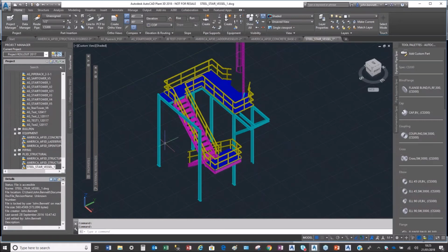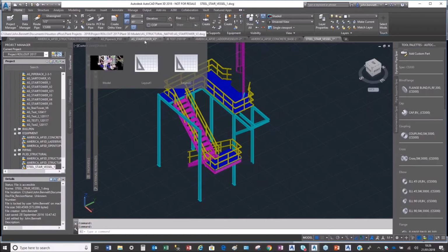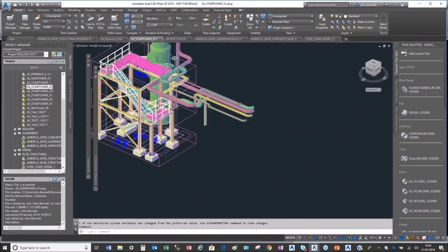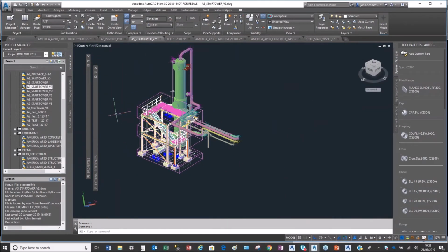So this is the example where someone's actually modeled this as a schematic inside Plant 3D to give the detailer an idea of what is required. Now, if you're doing this from a detail point of view, and I was to look at that in Advanced Steel, I would probably think, okay, I'd do the stair using a macro and I'd use a railing, so I don't really want to send all this out. And to be honest, I'm probably going to have to put a bunch of extra steel work in to do what I need.